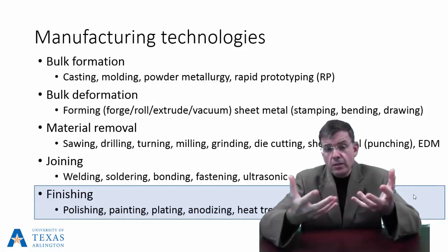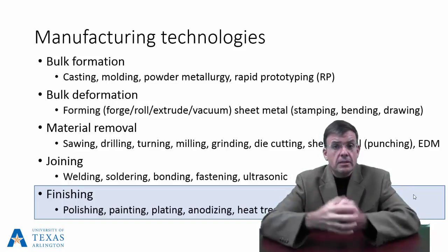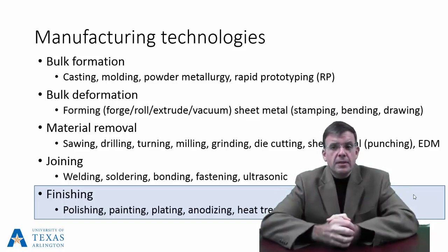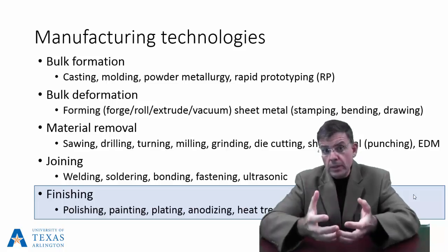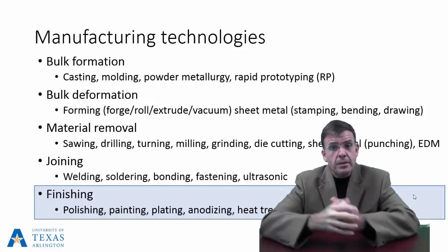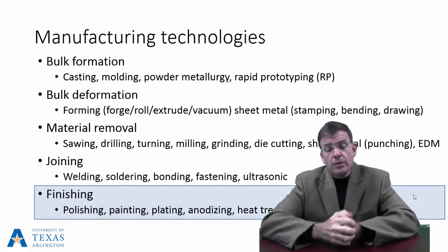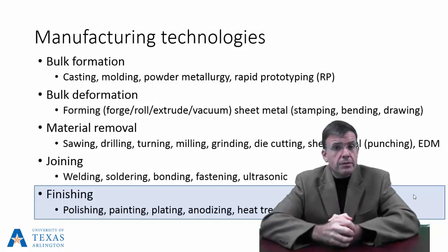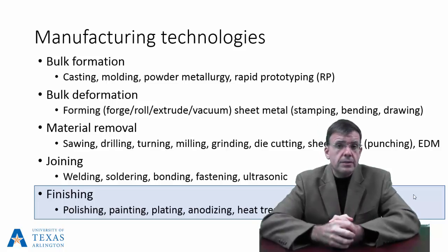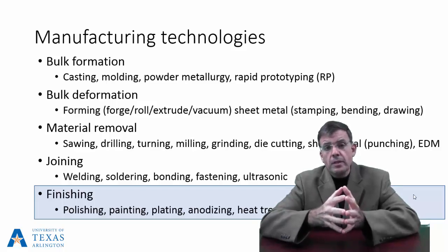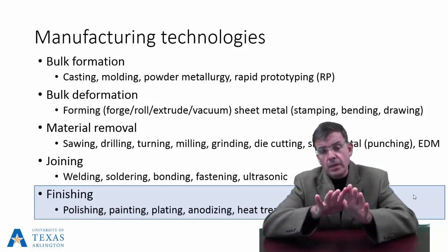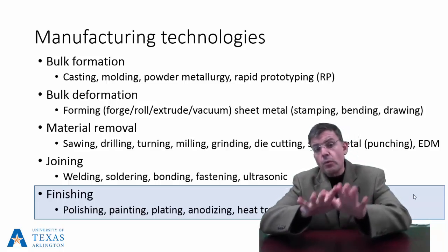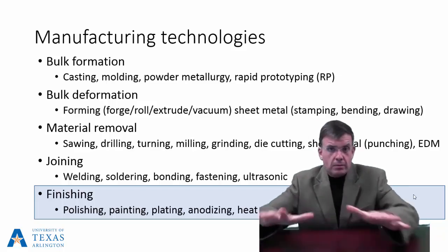Okay, a lot of times we paint, for that very reason. Okay, so steel is wonderful, inexpensive, but it has a nasty tendency to corrode. So painting will do that for you. We can also chrome plate something, perhaps even for appearance, not just for functional characteristics, but for aesthetic characteristics. Okay, we might want to impart a particular finish because of dimensional needs. Okay, so that would be the moving from grinding into polishing and lapping.